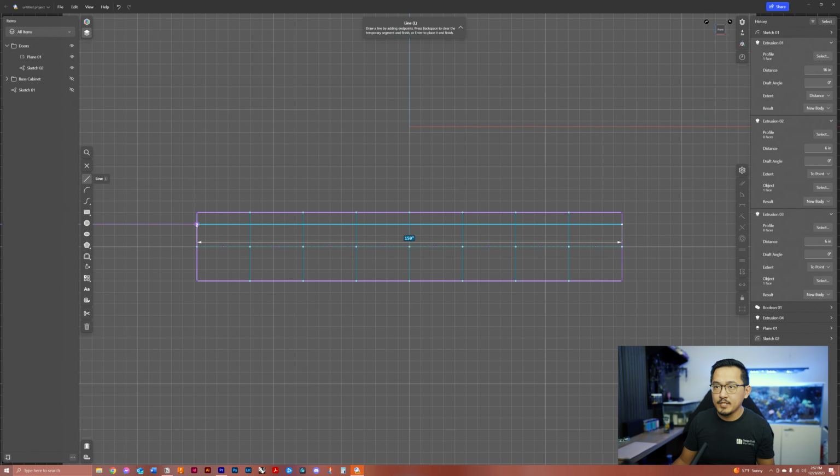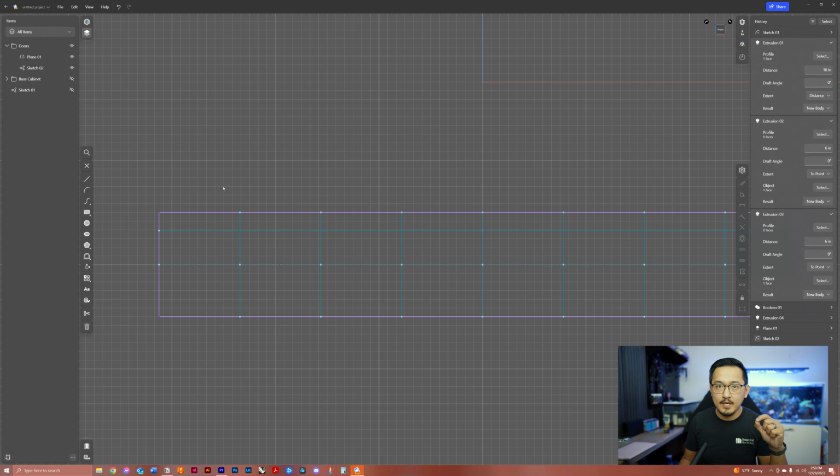at the top edge here. This line is going to be 1 inch below the countertop profile. So my profile is 3.5 inches. So what I'll do is I'll add 3.5 inches plus the 1 inch, and then I'll minus the material thickness of the countertop. That should give me the top height for my doors.